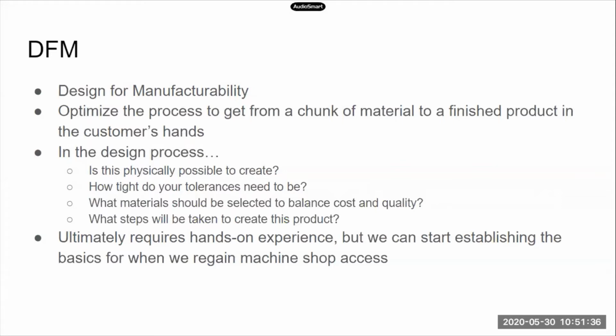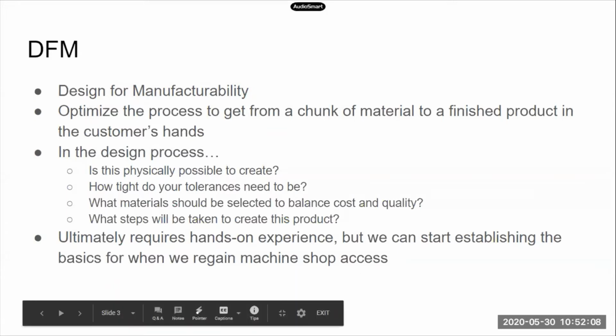And so let's say you only need something to the 10,000th, or you're doing something pretty standard that's not going into the aerospace industry, you're just making something in your house, and maybe it just needs to fit together. It doesn't need a super tight tolerance. So you don't need certain machinery that would be more precise. You can take higher depths of cut. You can maybe just use rougher processes.